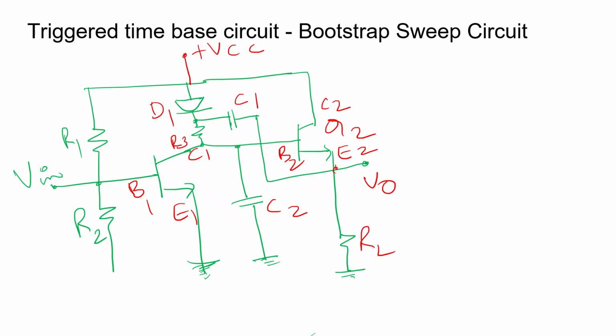From the start, the transistor Q1 is turned on because of biasing, and because of this, the capacitor C2 will be completely discharged through Q1, which in turn results in the output voltage becoming zero. Since the transistor Q1 is on by default, to turn it off, a negative trigger of duration Ts is given to the gate of the transistor Q1. A negative trigger is given in this manner.